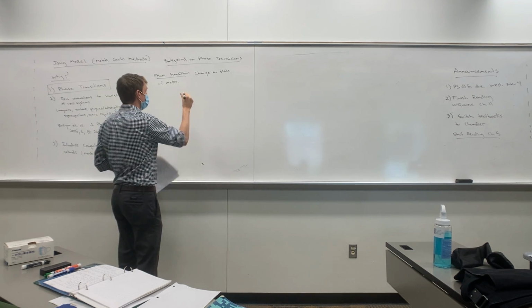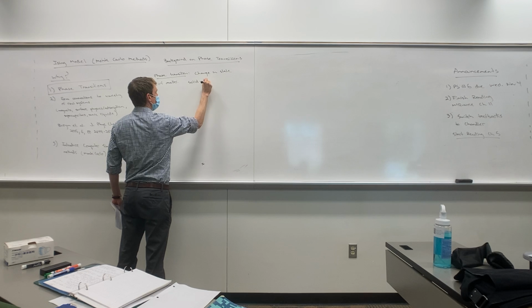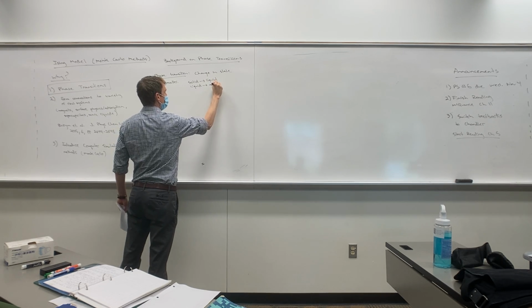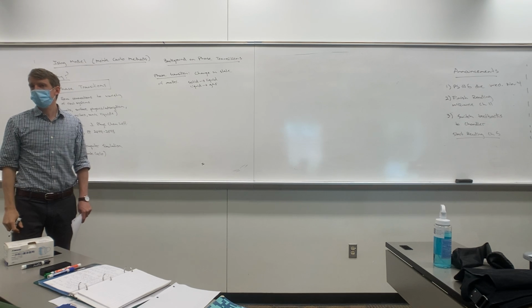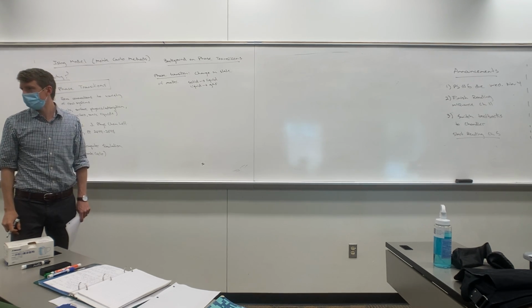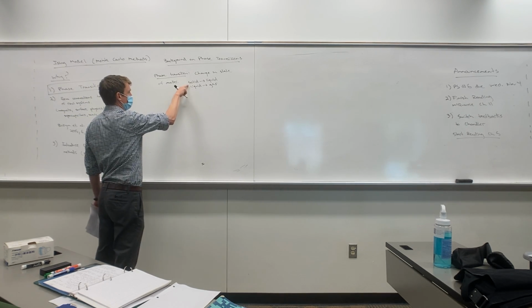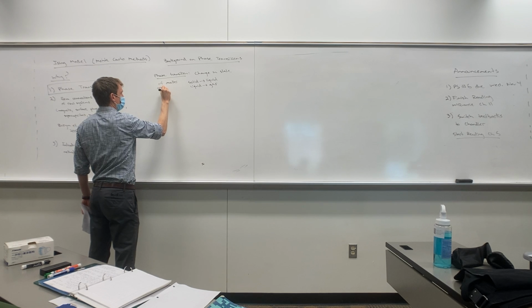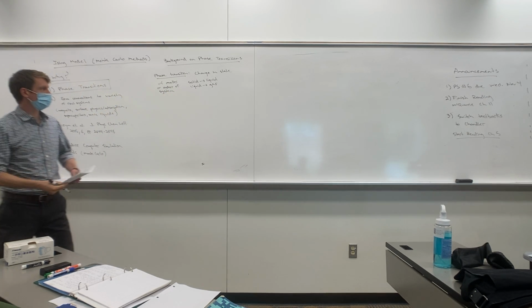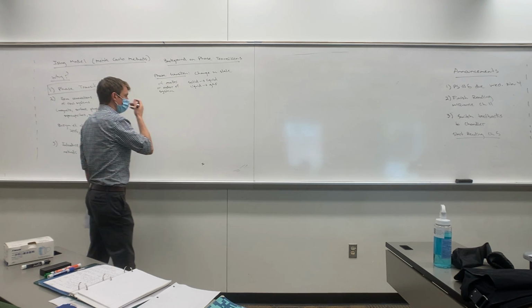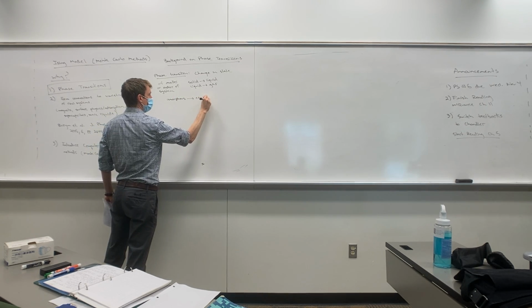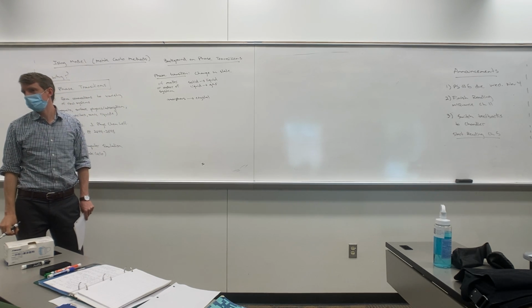And there's obvious examples and there's less obvious examples. And so, of course, your obvious examples are solid to liquid, liquid to gas, that's obvious. But there are more examples that are not so obvious. Like anytime you have a system that's ordered that goes to disordered, that's a phase transition too, right? So you don't necessarily have to change the state of matter, but the ordering or order of the system. Okay, so we need to make it more comprehensive. So this is obviously changing the state of matter, but we could also go from, say, amorphous to crystalline. Okay, that's a phase transition. Glass to a crystal is a phase transition, right?